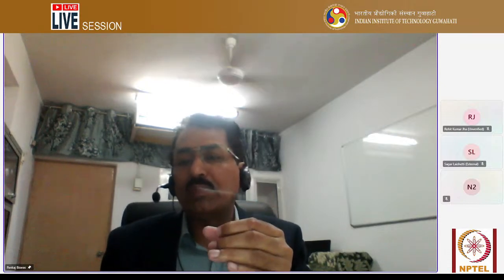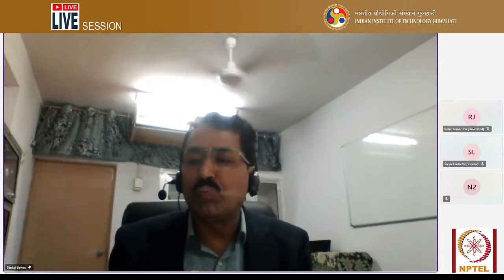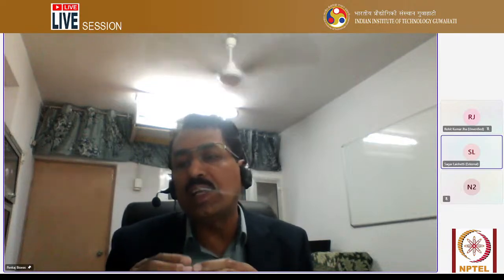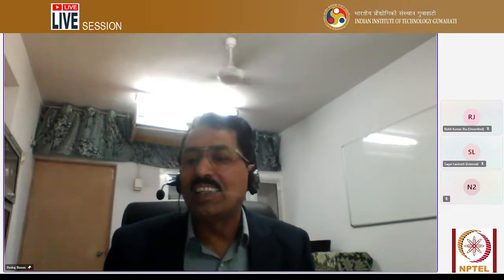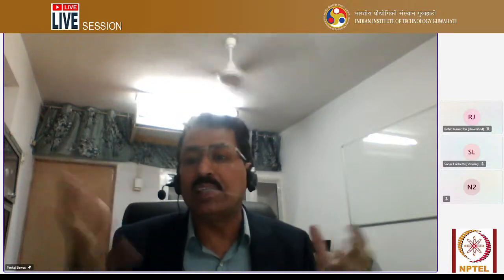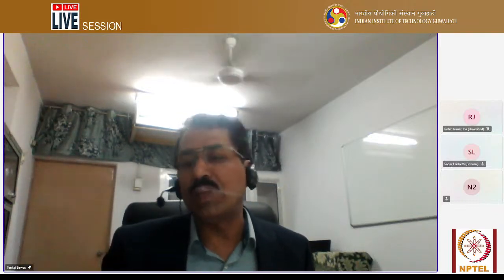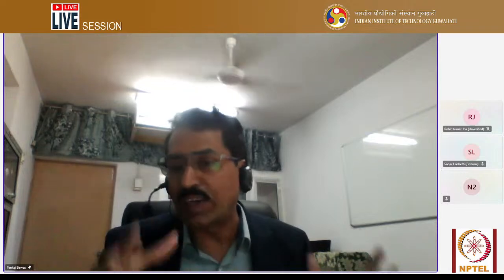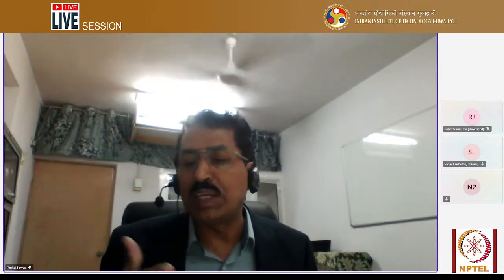Intensity of the arc means, let's say some heat is passing through a lower diameter arc, and the same heat is flowed over a larger diameter arc. The lower diameter arc will definitely produce a high intensity arc, correct? That high intensity arc can also increase the penetration. This is one case if you want penetration.